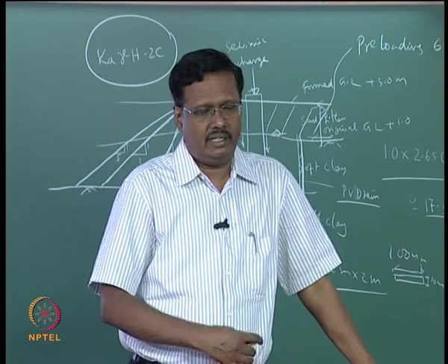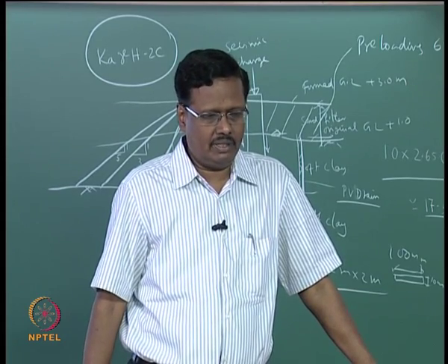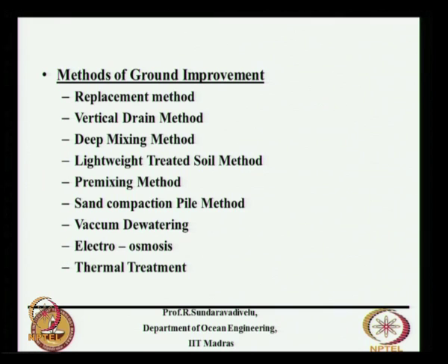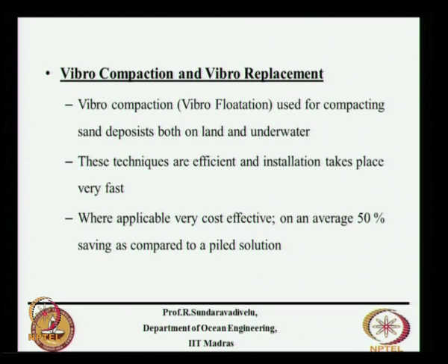For this condition it is very difficult to do, but we use some other methods that I will tell you. This is the method used for field conditions, vibro-compaction or vibro-flotation. This is for compacting sand deposits both on land as well as underwater. Jet grouting also can be done underwater. These techniques are efficient and installation takes place very fast. One of the main requirements for vibro-compaction is that it can be done very fast.